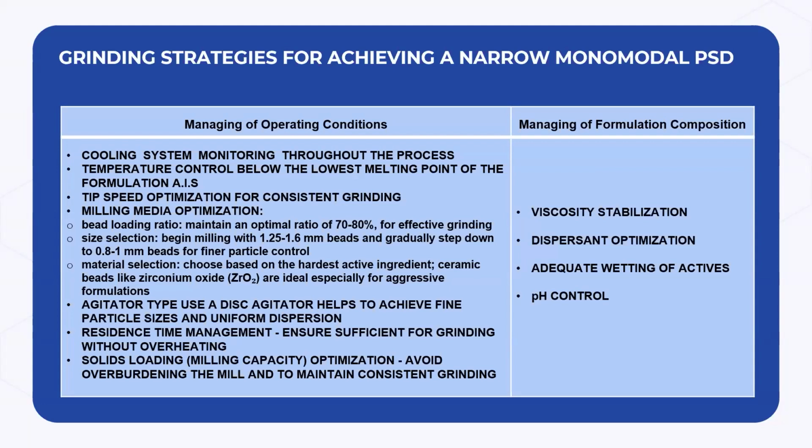Agitator type, using a disc agitator for effective shearing and grinding, achieving fine particles and uniform dispersion. Residence time ensures sufficient grinding without overheating. Solids loading balances the mill load to avoid exceeding capacity and maintain consistency.